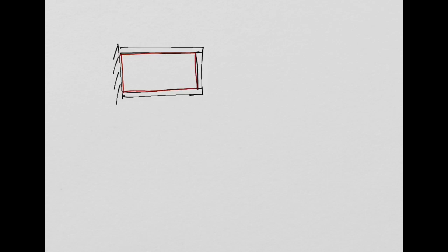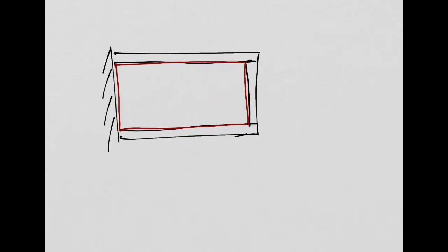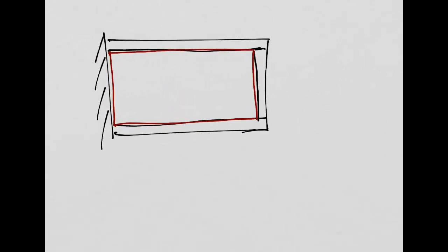As I told you, this web is carrying only a shear stress. So if I represent here, well, don't forget you are going to have a transverse shear force V. Yeah, and because of that, you are going to develop in this web a pure shear stress. You remember this from year 2, right? You did this in solid body mechanics, right?